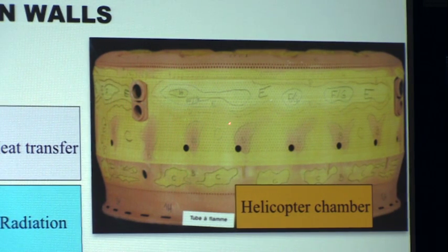And all the small things you see here are holes. They are what we call multi-perforation holes. And if you change one of them, you can kill the chamber. And really, you need to compute the combustion and the cooling system together because they are coupled if you really want to compute the chamber. If you go to Turbomeca or to Pratt & Whitney or General Electric, and you tell them you're going to compute a combustion chamber and you don't know how to handle the multi-perforation, they're just not going to talk to you. They'll say, come back when you know how to do it, because this is as important as combustion. So it's one more element that you need in your solver.